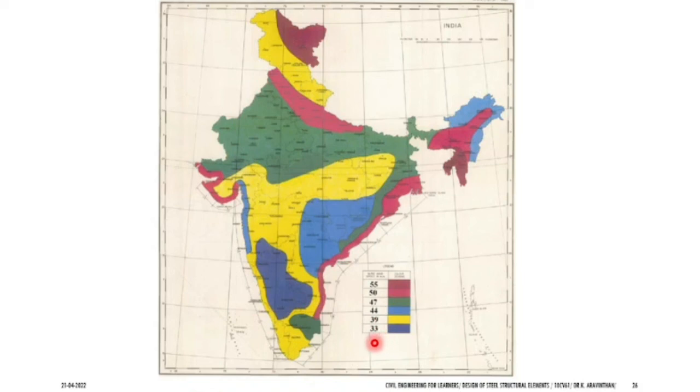You note it down. Whatever you are finding here, you note it. It will be very much useful. So when you are constructing in Bangalore, you can take highest wind as how much? 33 meter per second. So you can assume that the wind as the force and you can start constructing.